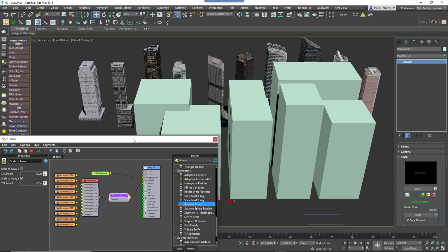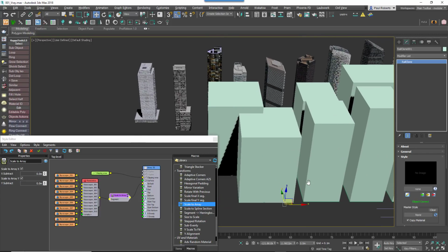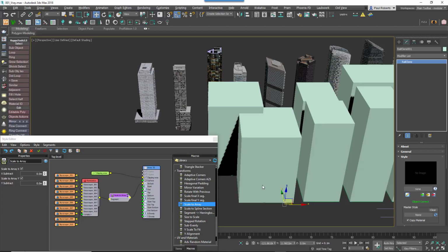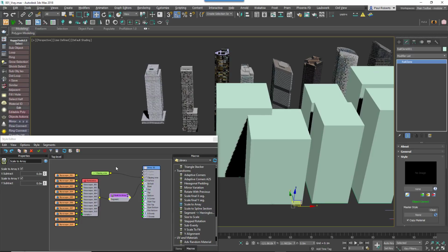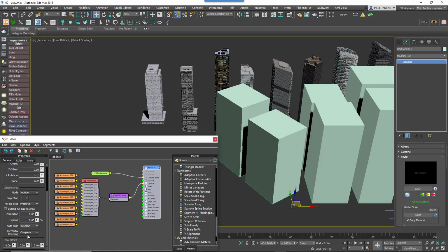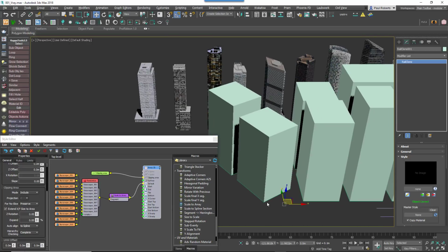This is all working well, but next we want to rotate the building to match the orientation of the spline. By default, the array's rotation will match that of the RailClone object. We want each array to rotate to match its subspline instead. To do this, open the generator settings and change auto align mode from none to spline. This mode calculates a direction vector based on the first and second vertices in a closed spline, and it uses it to align the array.